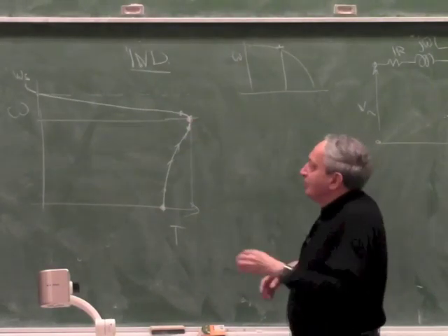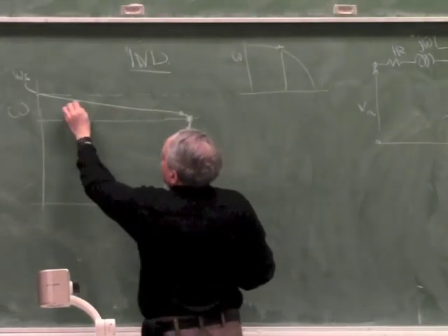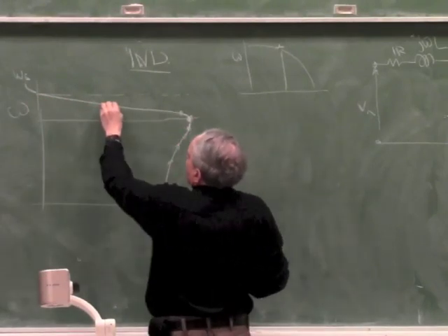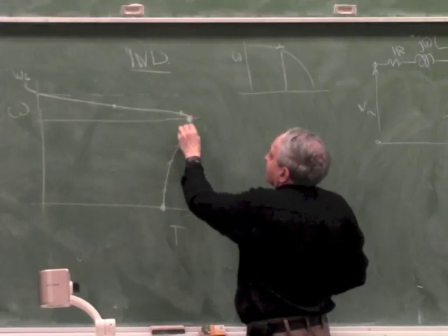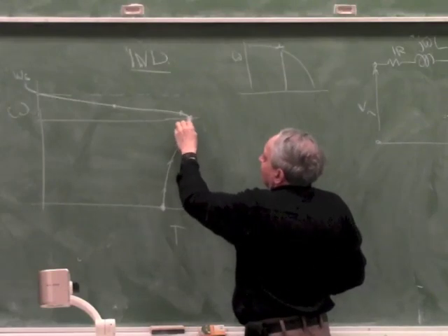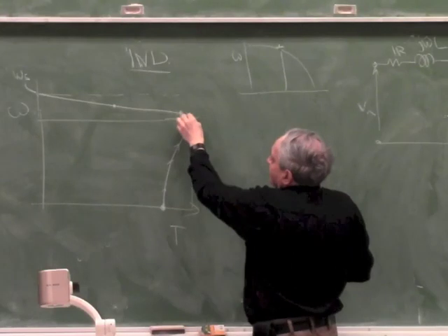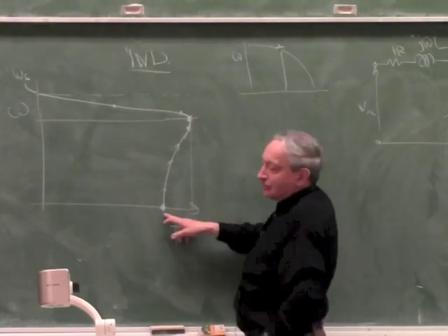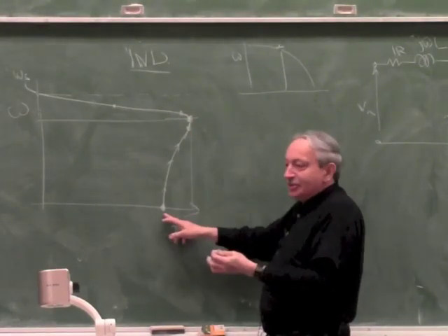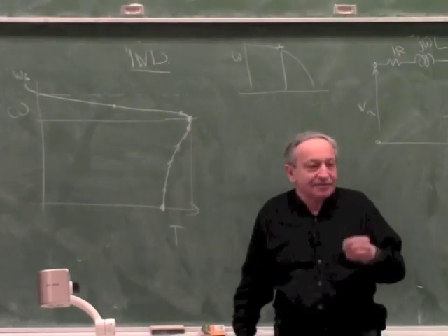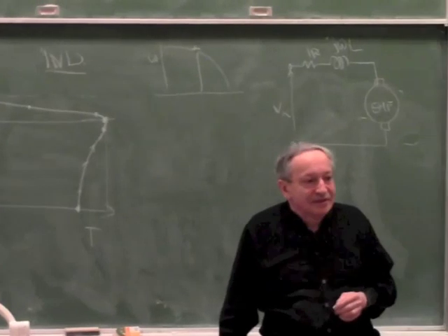If you take away the load, it will just run up here to a lower slip. Okay? So this is like a low load, and this is full load, and if you go too high above full load, it's not going to work. Because if you try to get the torque higher than this point, it's going to stall. But as soon as you remove the load, it'll climb back up. Yes? What's actually done to the motor to optimize it?